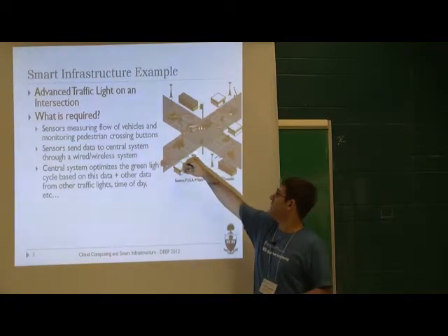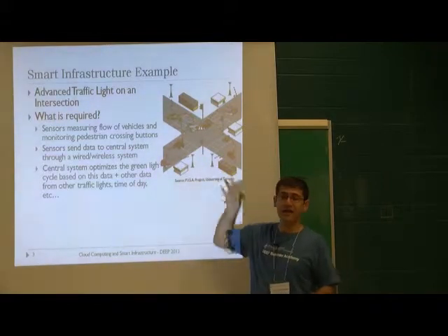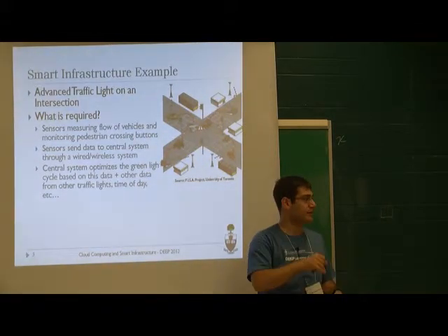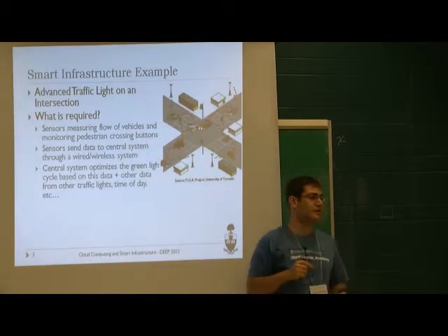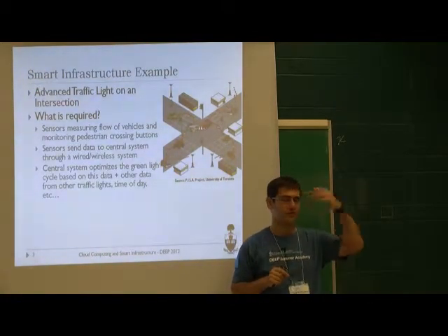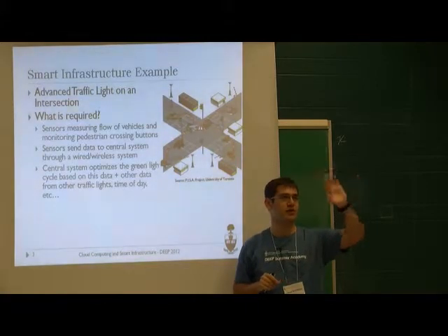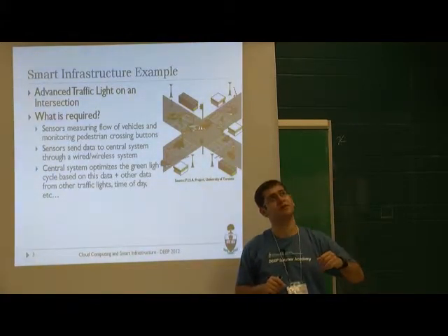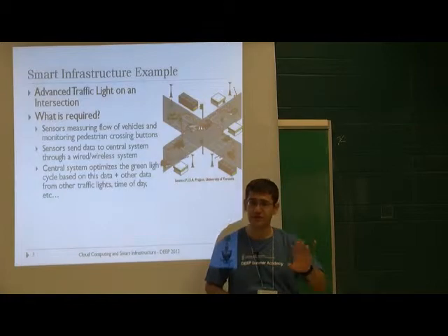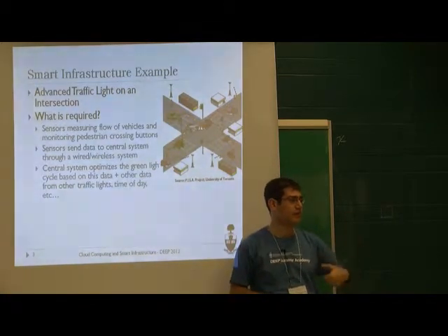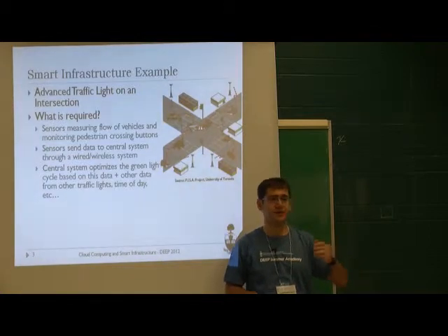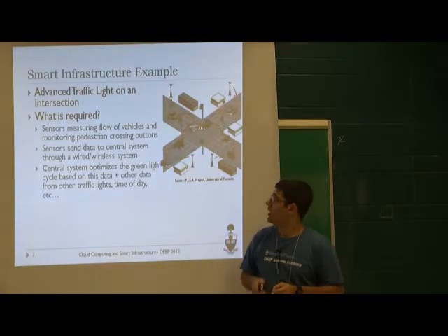When you press when the vehicle is ahead of that sensor or behind it, it will change immediately. Instead of the red for the pedestrian, you'll see a countdown. Instead of the green for the vehicle, you'll see a yellow or amber light for a few seconds, and then you'll be able to go through.